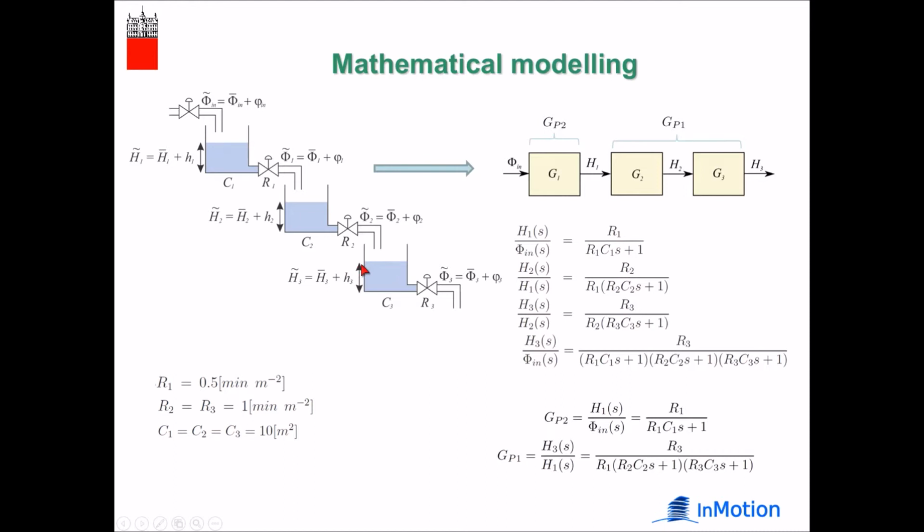And the control problem will be actually to define the desired or reference level with the control of the input flow. Because we shall also introduce the cascade control, we selected additional controlled variable, and therefore we grouped these 2 transfer functions into one transfer function.